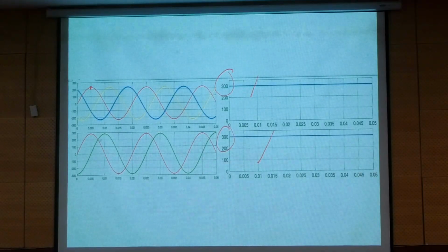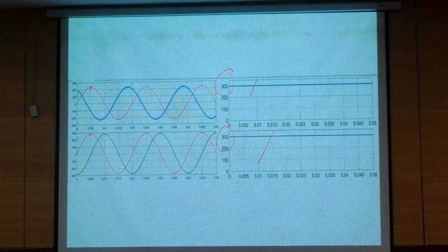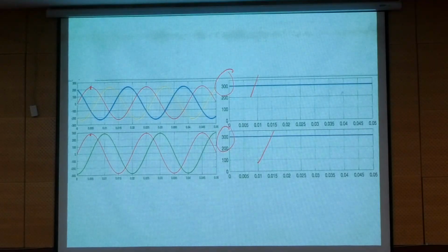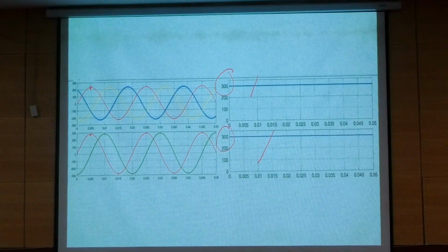220. But after converting the signals from 3 phase to 2 phase in power invariant condition, how much? It is close to 300. Magnitude is getting affected, but power is not getting affected. Right? So open your system, do fast, then we'll wind up today's session.